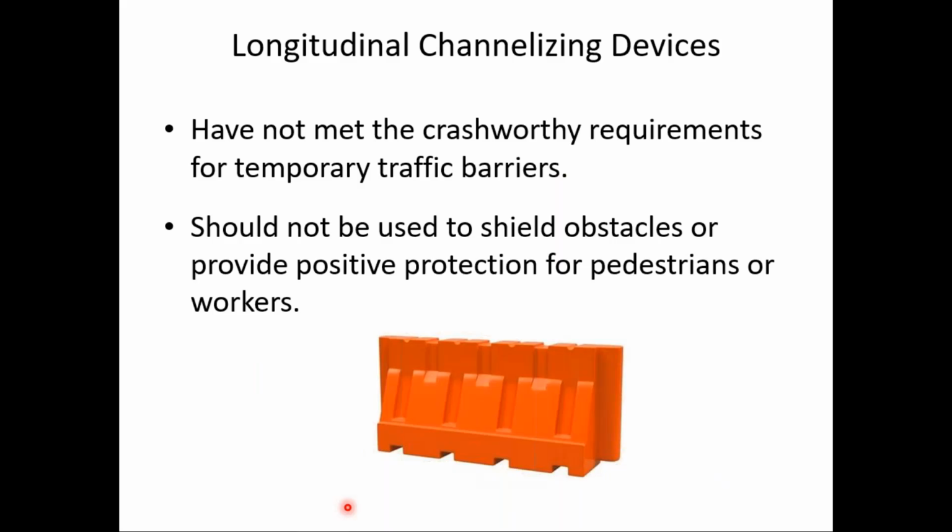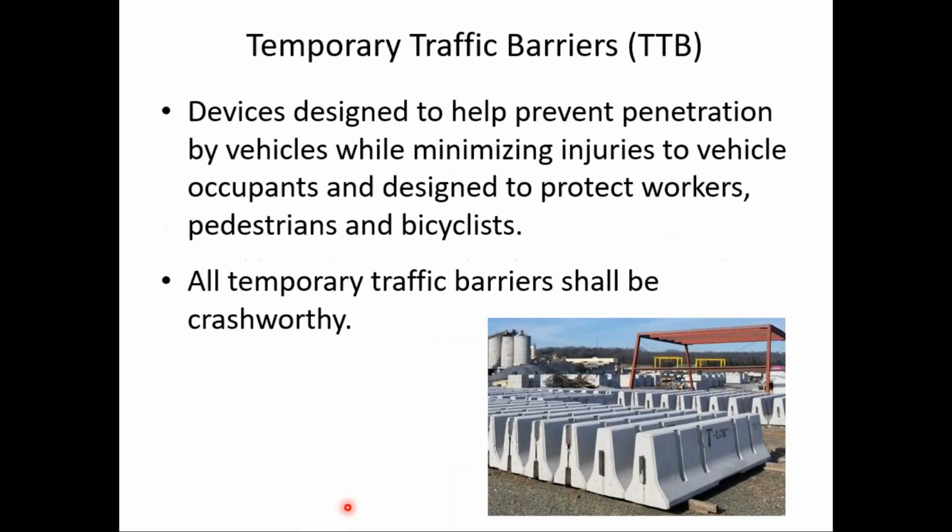I did want to note that these longitudinal channelizing devices, I call them sometimes pedestrian channelizers, have not met the crash-worthy requirements for temporary traffic barriers. So if your project calls for positive protection for workers or pedestrians, these are not the devices to use. These are pedestrian channelizers. They're not intended to shield obstacles or provide positive protection for pedestrians or workers.